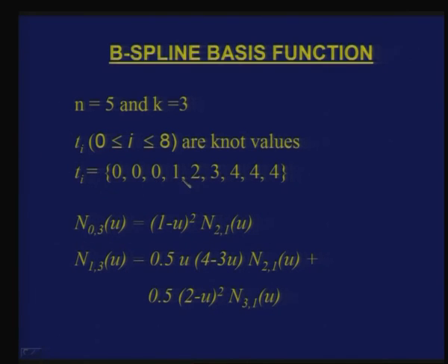If you see here, these are zeros at the ends, because k is equal to 3, and these 4 values are all 4s, the other 3 endpoints, and in between it is increasing in ascending order. So, the knot vector automatically comes up in the order which is required for a non-uniform B-spline curve definition.